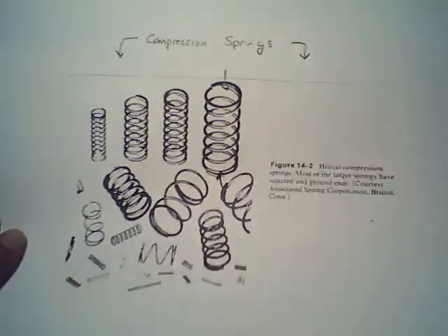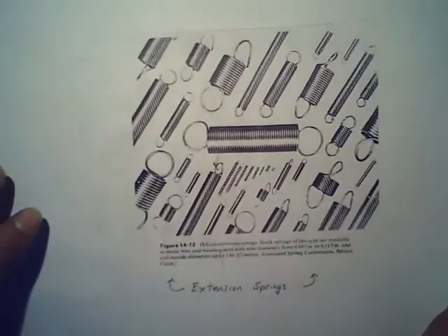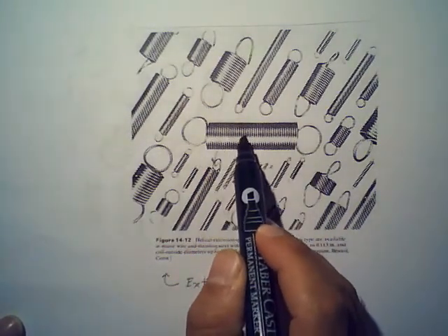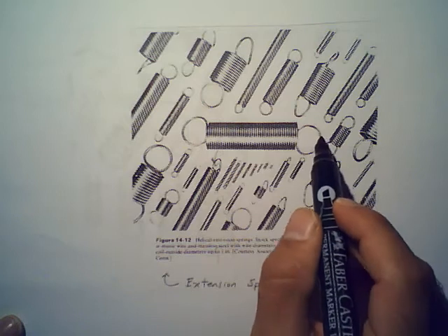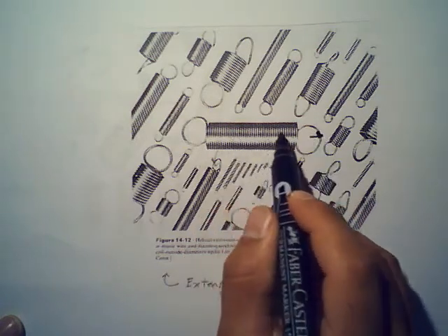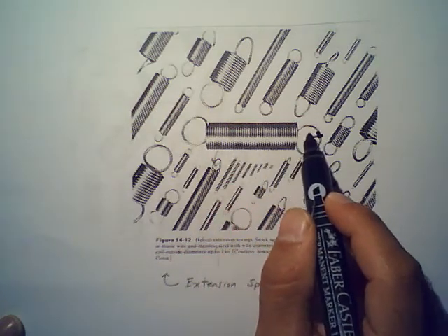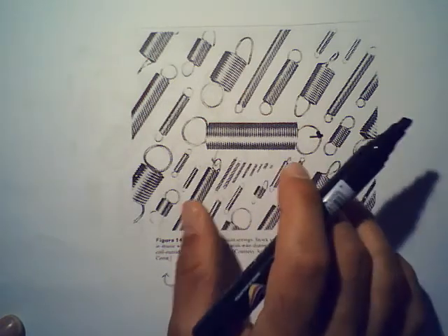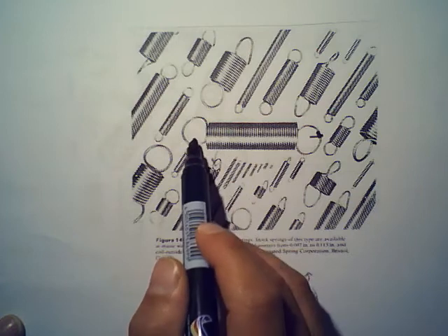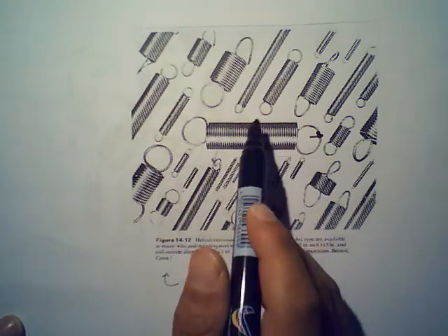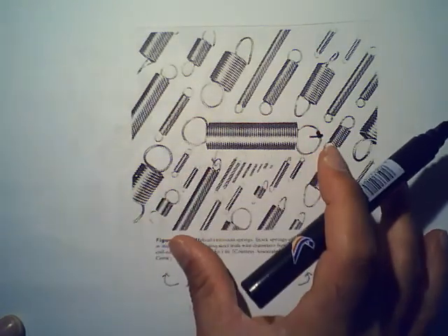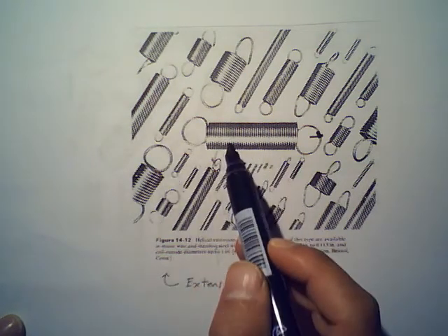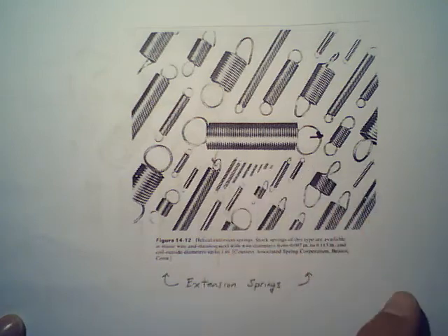And we also are going to be dealing with extension springs, and extension springs basically work in tension. So these extension springs are always in tension, right? Even if you apply some force on it, you won't open it up. You have to apply some force which is greater than the preload of that spring, and then that spring will open up. So depending on the application, sometimes you would want to have a tension spring to keep things in tension, and sometimes you would like to use compression springs. The failure analysis is relatively similar, but they will differ in certain aspects.